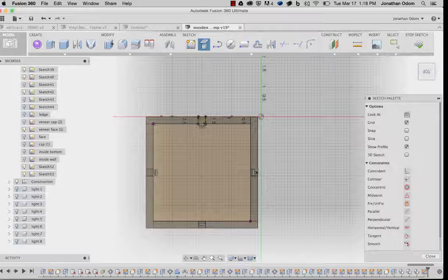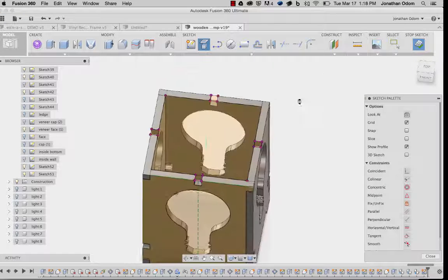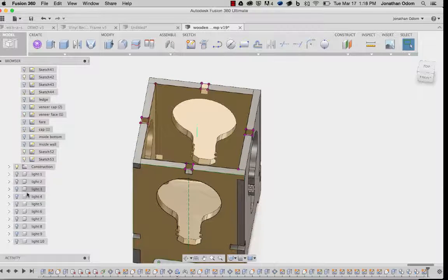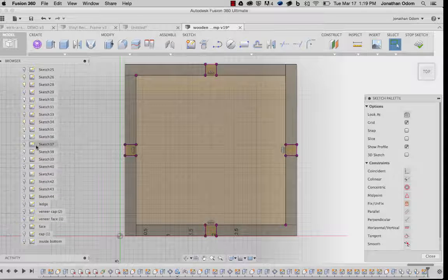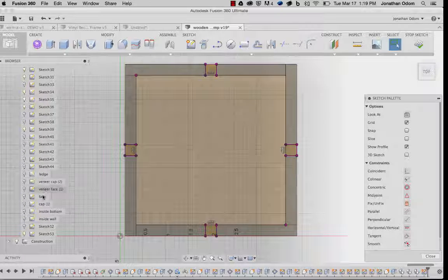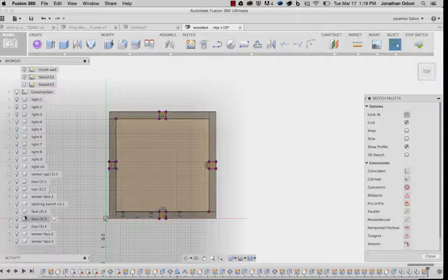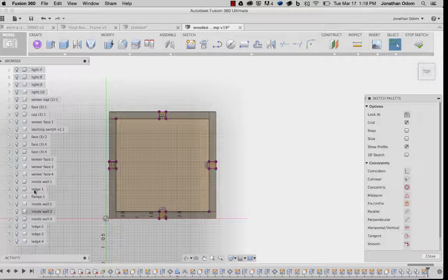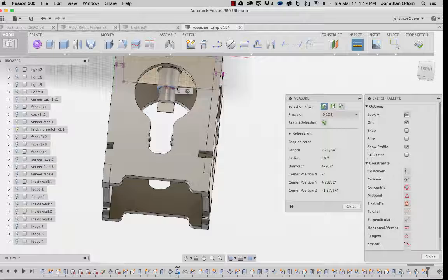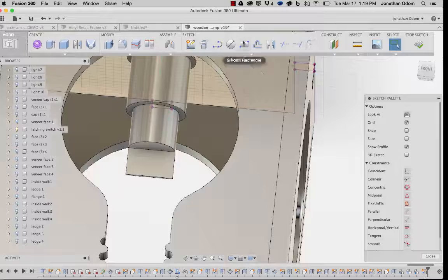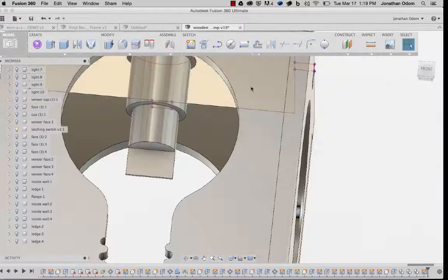I'm going to project these tabs here, and I'm going to see if I can't just rely on projecting old there to give me what I want. I believe I had a 3/4 inch hole here for the switch. In any case, I can just turn that switch on and see what the actual dimensions of the shaft of it are. Yeah, I made a little more space for it, so I'm just going to go ahead and project that. I can just use that circle.